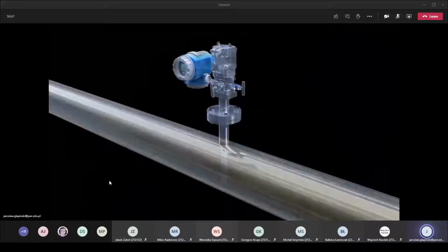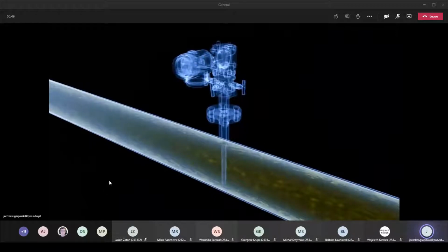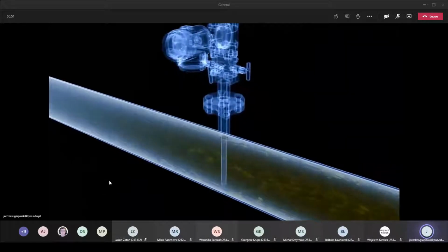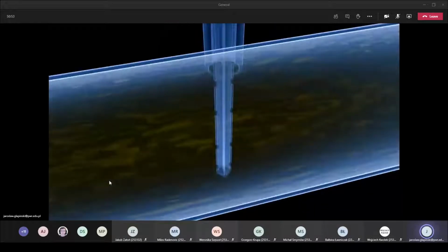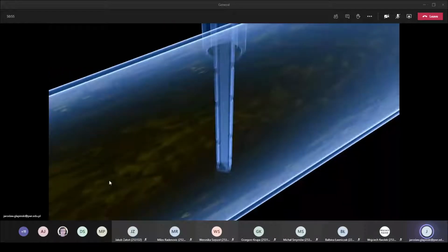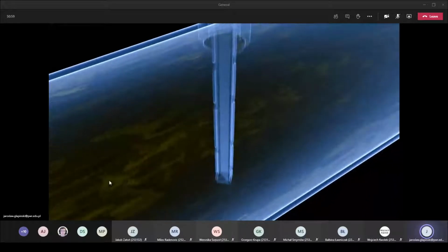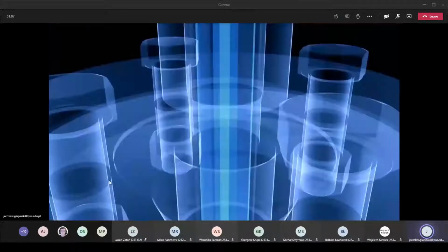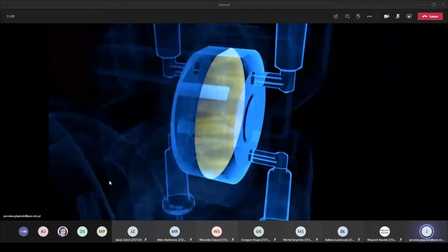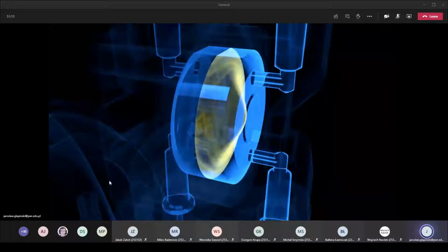Here is how this measurement method works. Pitot tubes have a rod-shaped measuring element that is inserted into the pipeline perpendicular to the flow direction. On the front and rear of this probe are several holes. Two separate tubes connect these holes to a differential pressure sensor. With its two pressure chambers, separated by a diaphragm, the tiniest pressure differences in the flowing fluid can be precisely measured.